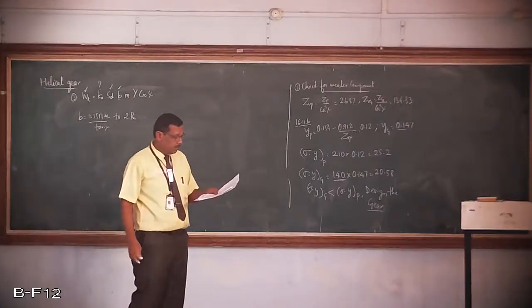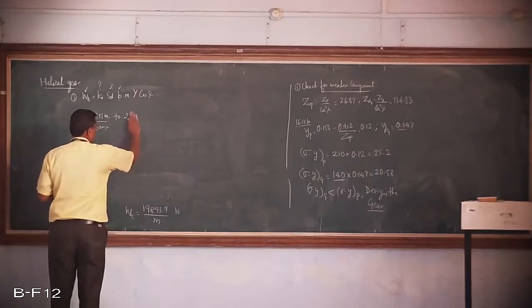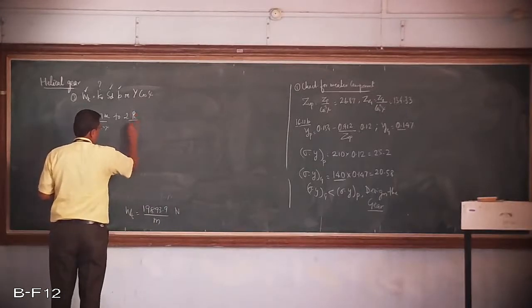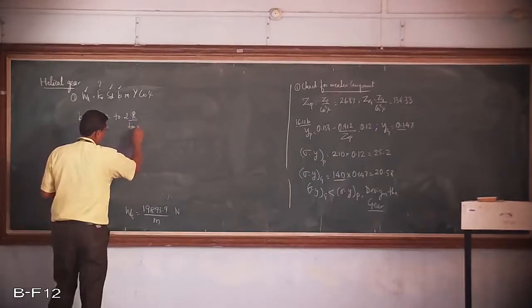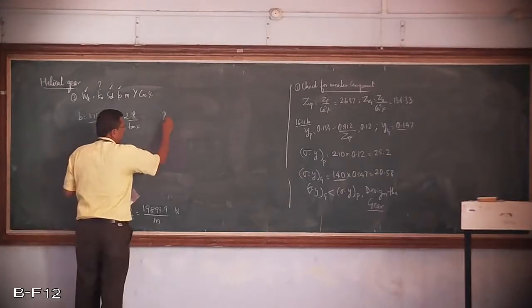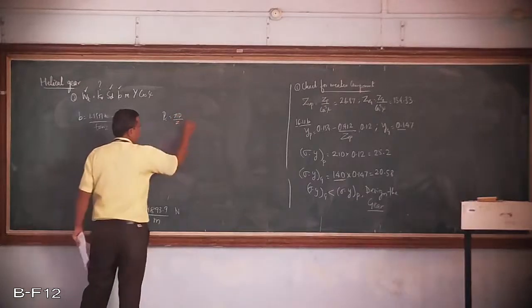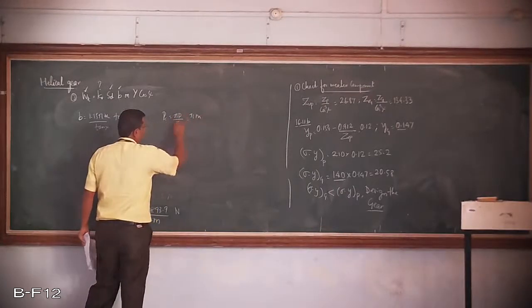Axial pitch is nothing but circular pitch divided by tan phi. Therefore, the equation becomes PC divided by tan of phi. And we know the value of PC. PC is equal to circumference divided by Z, that is equal to pi times the module, because d by Z is module.